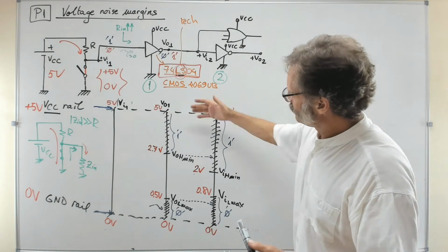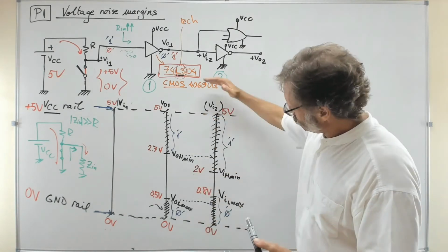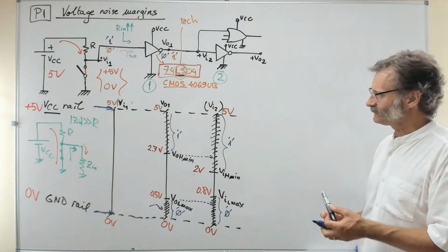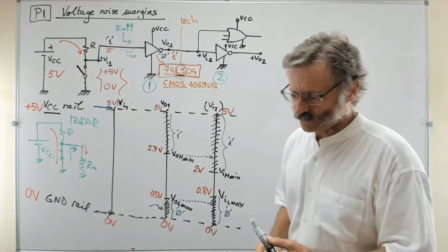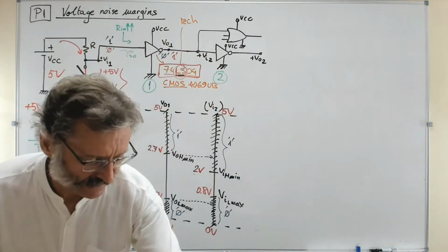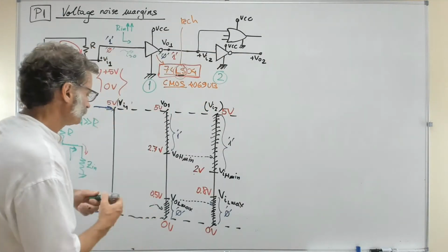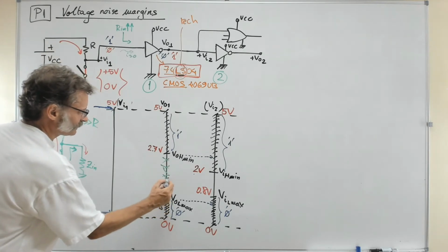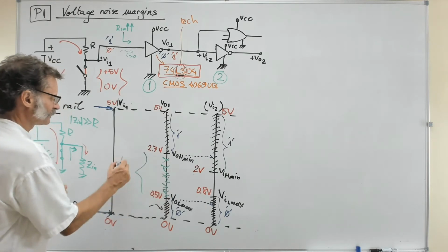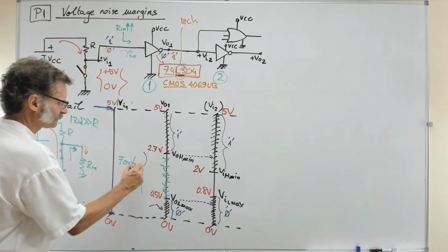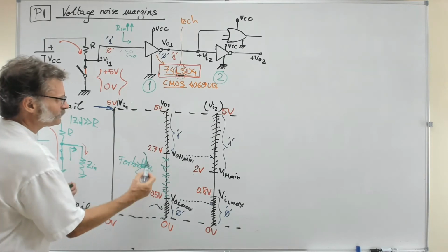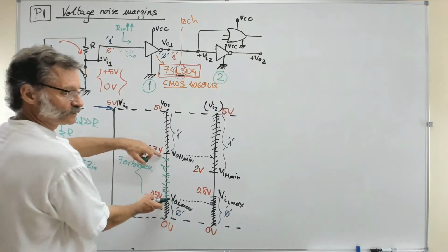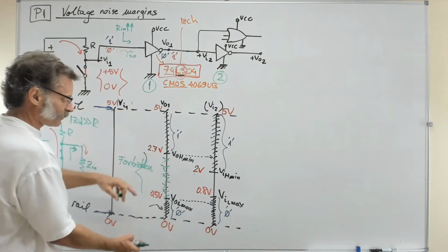You have the axis, you see the situation now. I guess that you have understood that very well. So what goes next now is to imagine the forbidden zones. Like this, this zone here is forbidden. You'd better never use it for anything. This is forbidden. Working with this margin of voltages, a margin of voltages that is not clearly a 0 or a 1, has no meaning.